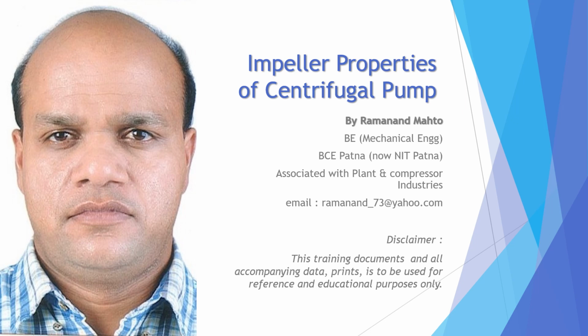I have selected the topic of discussion, which is the properties of impeller of centrifugal pump. Based on my experience, the properties of impeller of centrifugal pump topic is very important as far as design and sizing of pump is concerned. As you know, the main properties of impeller are specific speed, head coefficient, and inlet flow coefficient.